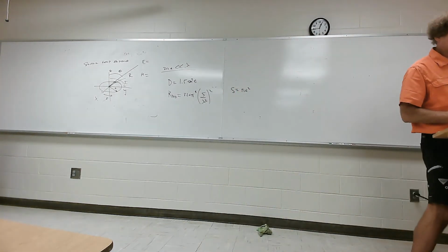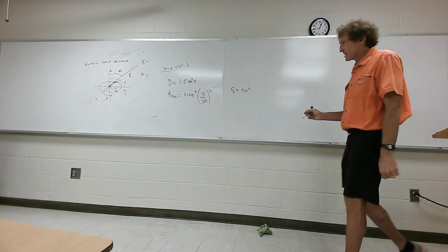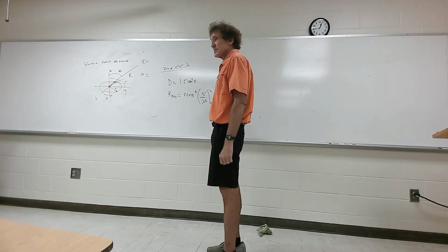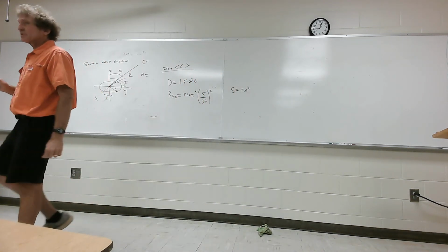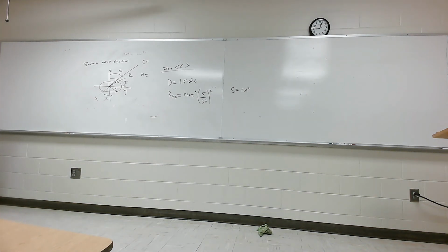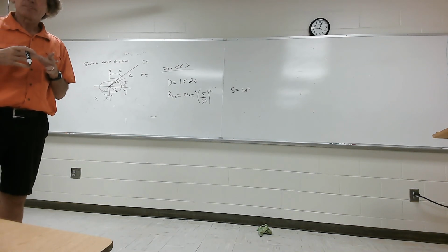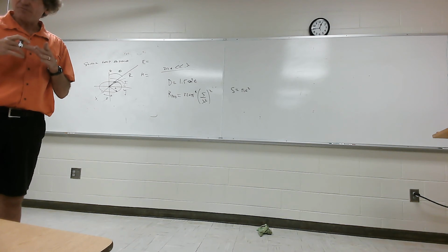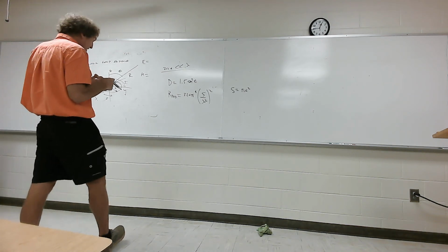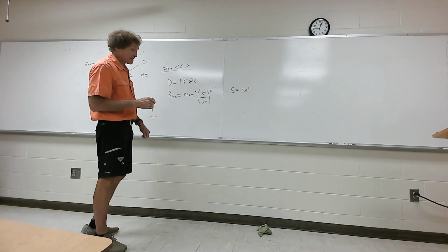But I have to tell you, there's more to this, and I want to just finish the lecture here. That's the radiation resistance for one turn, in other words, one loop. Most of the time, when you're dealing with small loop antennas, they'll have many turns, 50, 100 or more. So the total resistance goes up by the number. If one loop had 100 ohms, 2 loops would have 200 ohms, 10 loops would have 1,000 ohms. Y'all follow me? It's a linear addition, and I'll give you a formula about that.